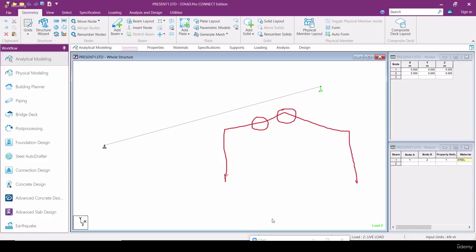For example, before going to the global deflection, there will be deflection in the column also, because you are applying the load vertically downward. If it deforms like this, the column will tend to move in this direction, so it will also cause some extra deflection in this beam, which we can call secondary deflection.